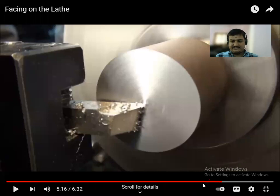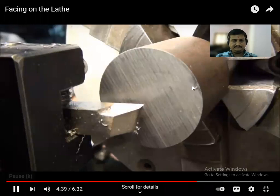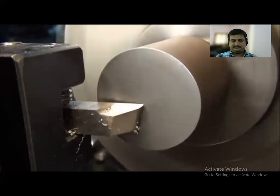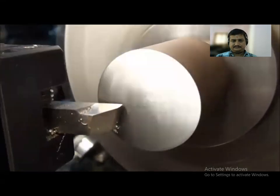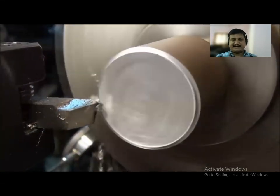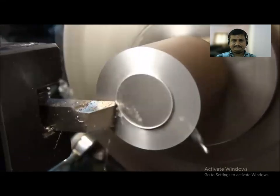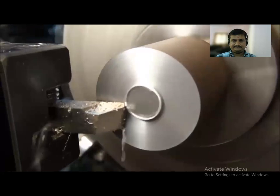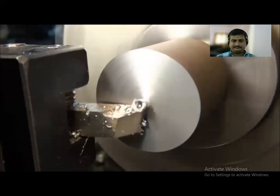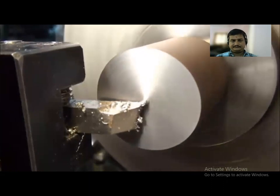Okay, once again you can see this operation. Make sure we have enough RPM as we get close to the center of the stock. Okay, for roughing out, for rough cutting, I like to start on the outside and feed in. On speed, the cutting is started. Just clean out most of that saw cut. Okay, then we can tell how far we are off on center. It looks like we're a little bit low, so let's raise it up a little bit so we get rid of that little.